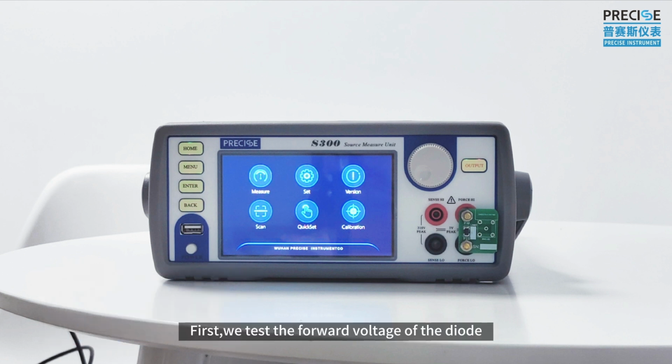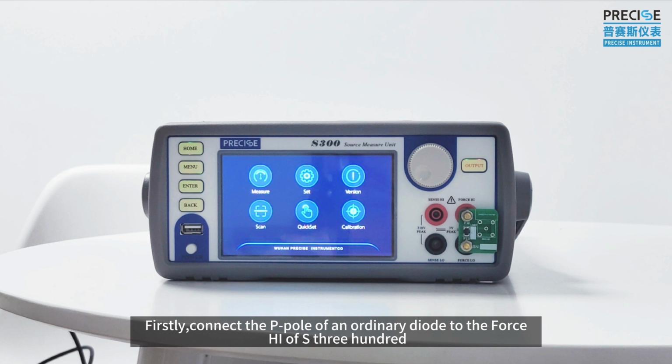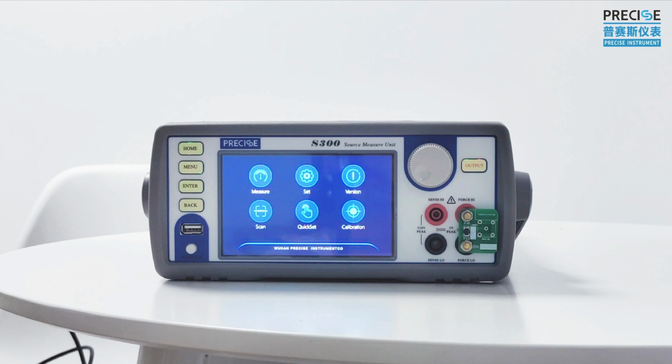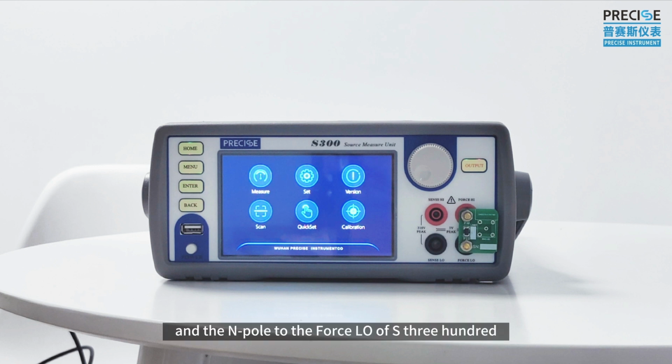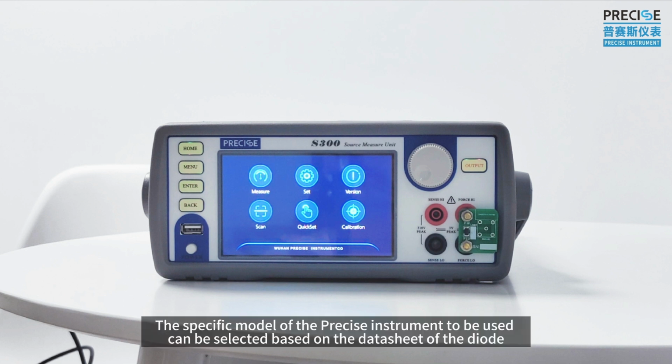First, we test the forward voltage of the diode. Firstly, connect the P pole of an ordinary diode to the force high of the S300 and the N pole to the force low of the S300. The specific model of the Precise instrument to be used can be selected based on the datasheet of the diode.